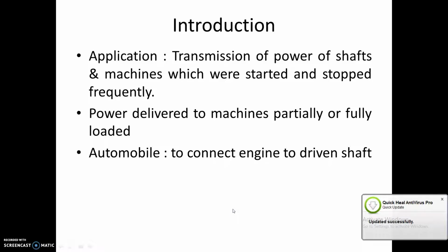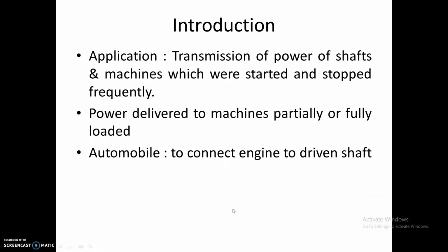When the clutch is disengaged, the power is not transmitted to the driving wheels and the vehicle stops while the engine is still running. In a vehicle, the clutch is always in an engaged position. The clutch is disengaged during gear shifting, while stopping the vehicle or during braking, and when idling the engine. It should be disengaged by operating the clutch pedal. When the clutch is operated properly, it prevents sudden jerk motion of the vehicle and thus avoids putting strain on the remaining parts of the power transmission.